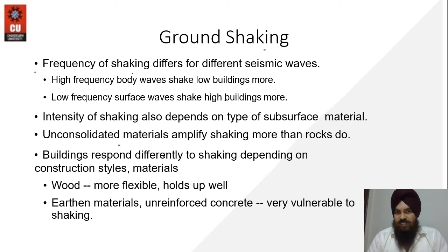Construction style, meaning the shape of the building, is also one of the factors which respond differently to shaking. Secondly, the material: steel structures are more ductile than RCC or timber structures, so they have more ability to take shock waves as compared to rigid structures like